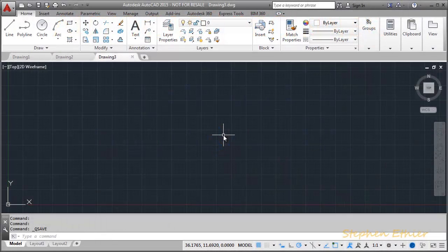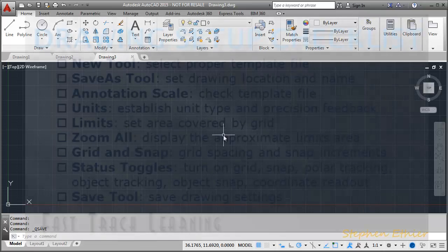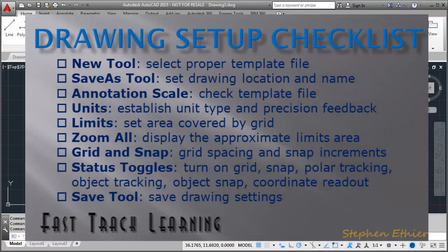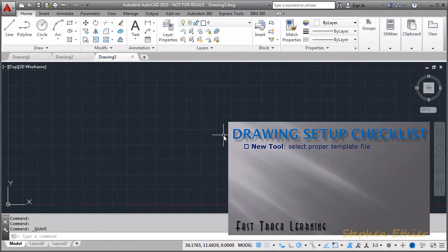The first step in creating drawings in AutoCAD is to learn how to tell AutoCAD what you want to happen and how AutoCAD responds back to you. You will start by using an initial template file to establish the proper drawing measurement units, and then adjust some settings to control the input from you and the output from AutoCAD. You will also be adding to the tools you already know to begin drawing some geometry.